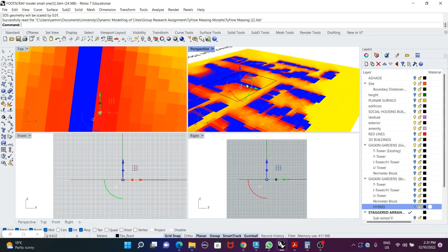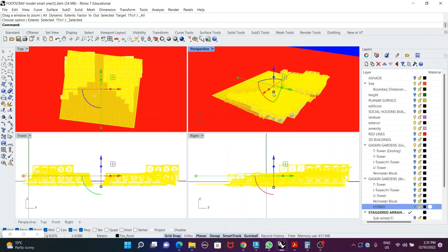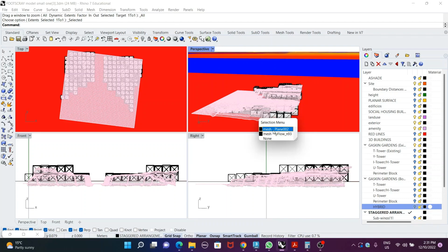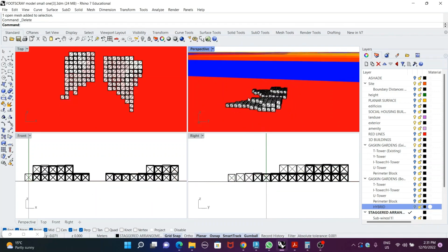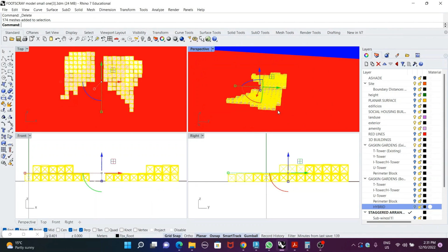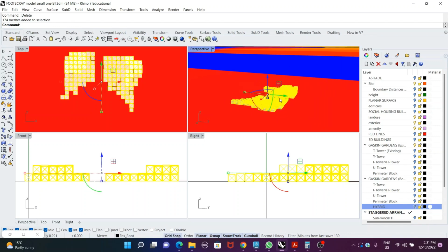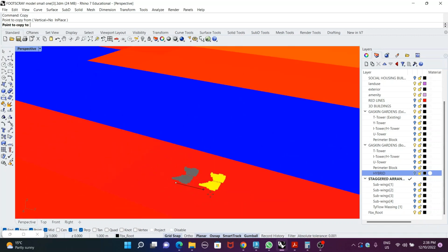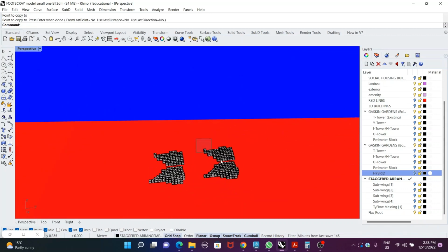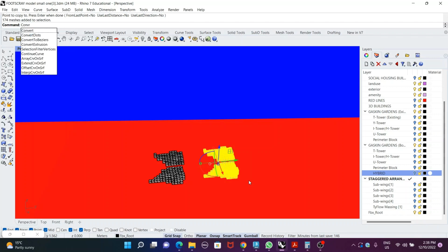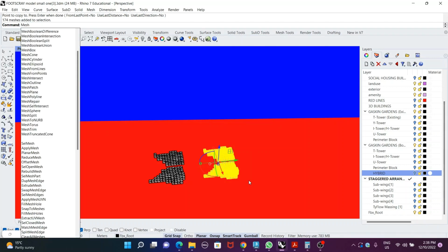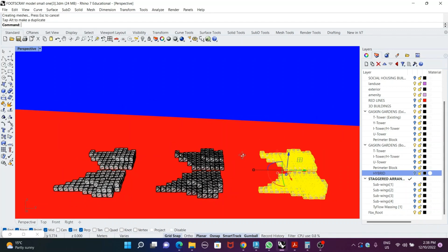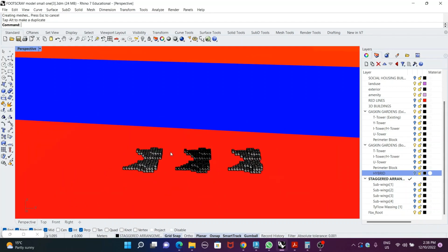We've obviously got a scale mismatch going on here. That's okay. What we're going to do is we probably don't need that mesh, so we'll delete that. And then all of these are currently as meshes, and we're going to convert, go mesh to NURBS. Those out. So here's all of our poly surfaces.